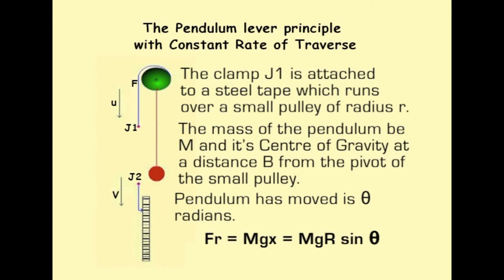The effect of extension on the loading of the specimen cannot be ignored, and the rate of loading and the time to break are influenced by the extension of the specimen. The velocity of the upper jaw is less than that of the lower jaw by an amount depending upon the extensible properties of the material. So, by adjusting these two, the effect of this extension can be overcome.